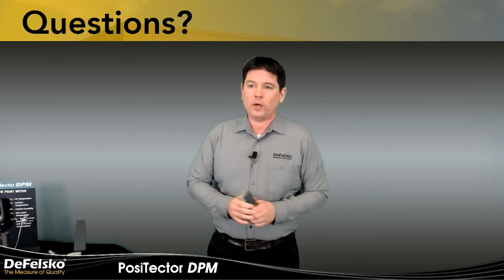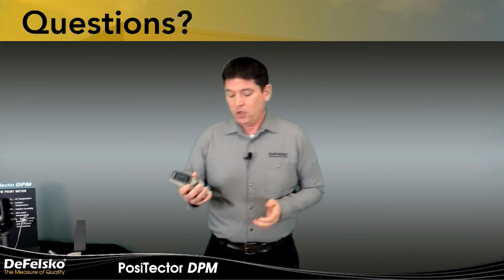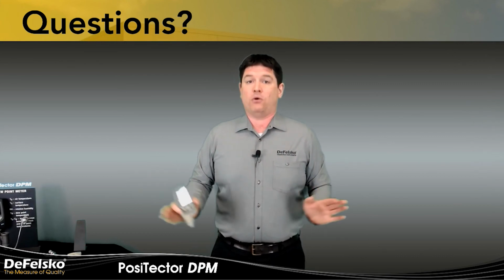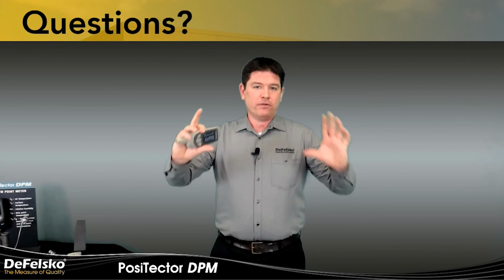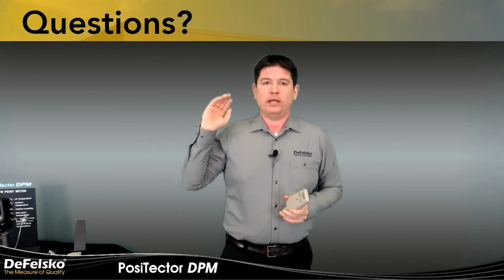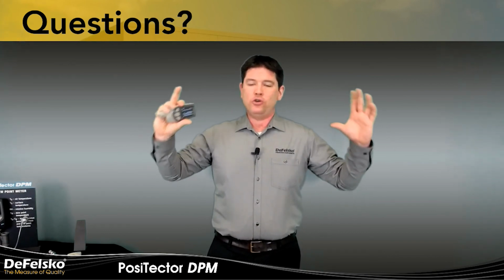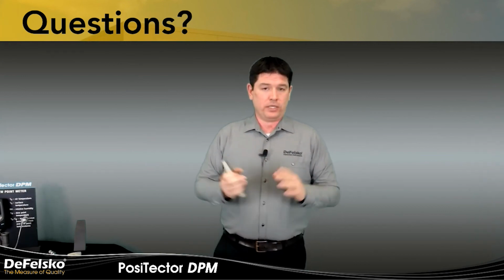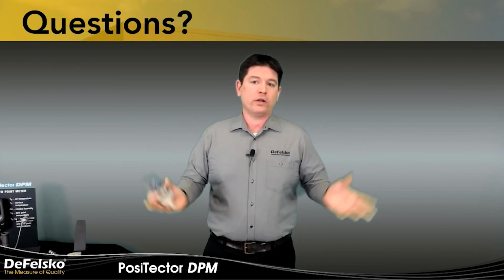I see we do have another question that just came in that said, what is the maximum measuring distance with the new IR? Well, really the answer is it will measure quite a ways out, but what you have to keep in mind is it's averaging everything that's coming in on that cone. So if I'm measuring 10 feet away, I'm measuring a spot that is 2.5 feet in diameter. If I'm measuring further than that, you can tell that spot keeps blowing up. So the further you go out, the more area you're measuring.